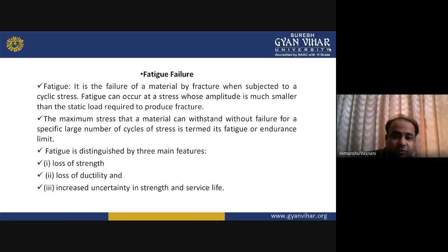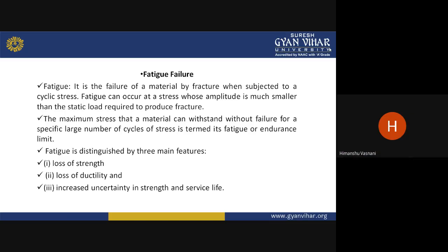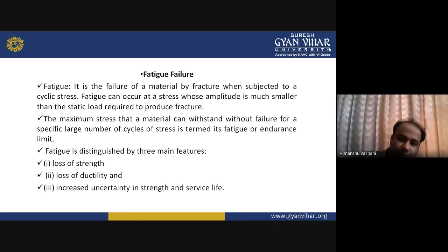Fatigue can occur at a stress whose amplitude is much smaller than the static load required to produce failure. The maximum stress that a material can withstand without failure for a specified large number of cycles of stress is termed the fatigue or endurance limit.